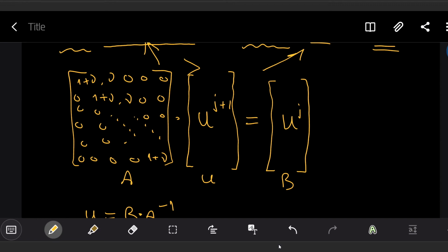The smaller the Courant number, the better the stability of the solution, but at the same time we have a slower solution. With a bigger Courant number, we receive the solution faster, but it can break at some moment, because if we make the value of the Courant number too big, it will be unstable. More about stability of the computational model is in the lecture. It's very deep mathematics, not something simple, and I'm not sure you study this level of mathematics at the university, but you can try to read. It's functional analysis, quite interesting, and complex function analysis.